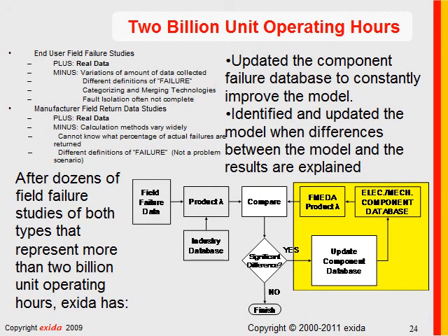But in this application, leakage across the screw terminals increased the 4 to 20 milliamp current level. And if you have a low trip, that's a dangerous failure because the transmitter current will not reflect the process variable until the process variable is much lower than the trip point.